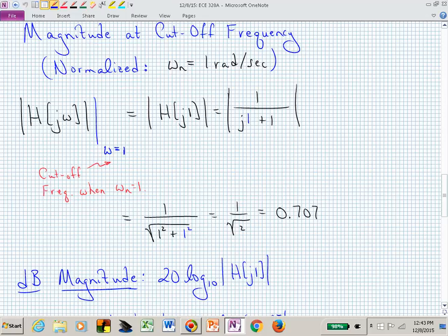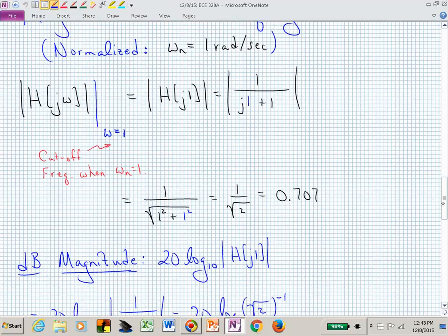I'm showing you the hypotenuse. I'm not directing the choir, although I could be. And what are we doing? We're getting higher and higher frequencies, aren't we? Which is maybe what that section needs to be giving me. So the magnitude could be asked in absolute terms, or it could be in dB. If we find it in dB, we take 20 log of that number.